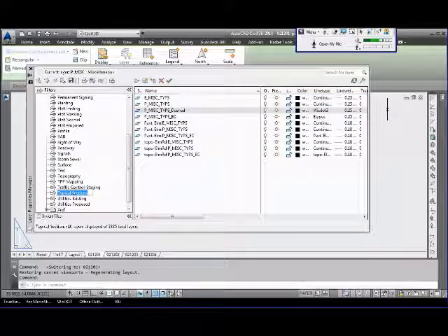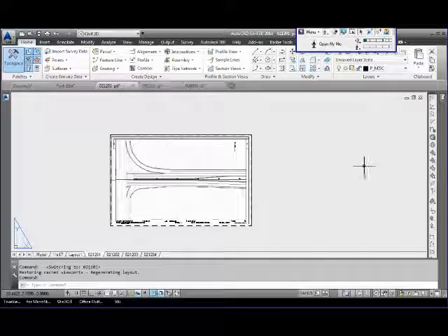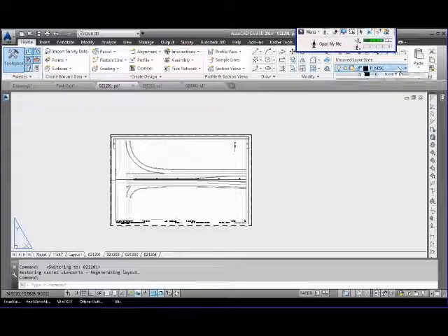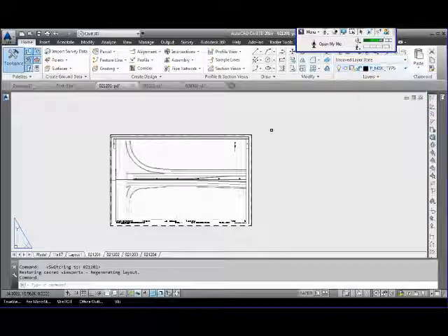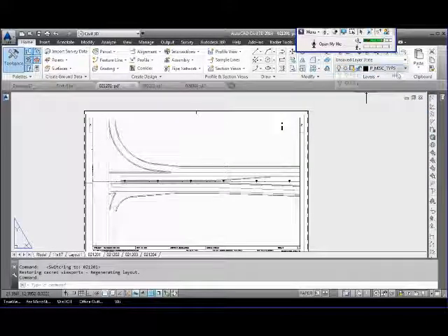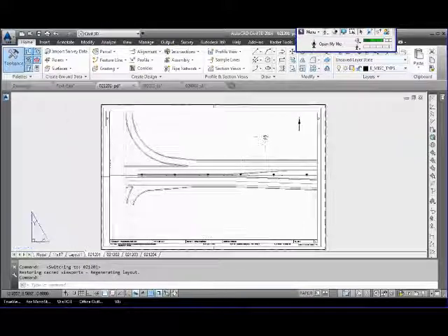If I was working on that and I was switching layers a lot, if I turn that layer filter on, I close the layer manager, and I come up to the drop down of all your layers, it recognizes that layer filter that you just turned on. You can use the layer filter without having the layer manager open. So it would be an easy way to flip between to make your active layer proposed, miscellaneous, existing, whatever you want.